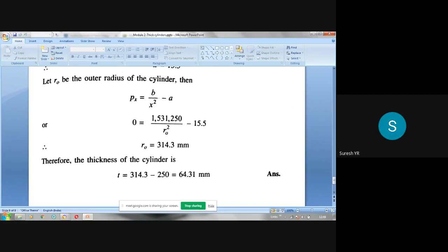Mainly we are dealing with simply supported beams and cantilever beams. Module 3 is finding the bending moment and shear force in simply supported beams and cantilever beams subjected to these types of loads: concentrated load, UDL, UVL, trapezoidal load, and couple or a moment. So I want you to study those equilibrium equations as well as how to find support reactions.